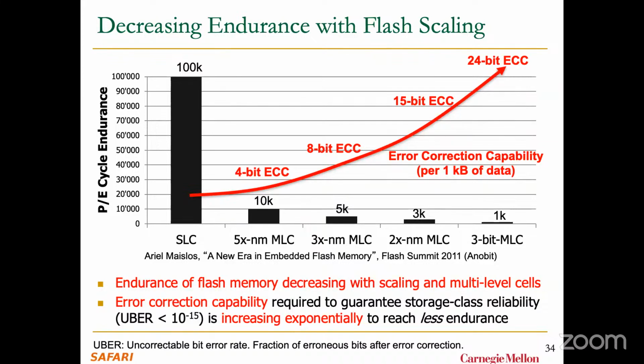So your flash chips are going to get more expensive and more costly when you want, for example, to have this 3-bit MLC, which is TLC actually. MLC is multi-level cell, but mostly in papers, when they say MLC, they mean 2 bits per cell. For 3 bits per cell, we use TLC, which is triple level cell. And for 4 bits, we use QLC.